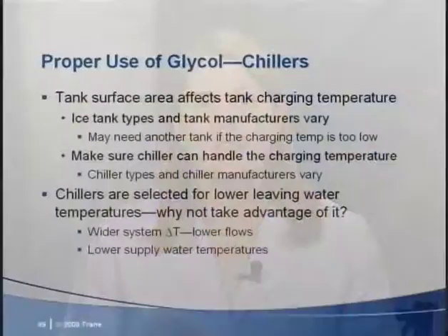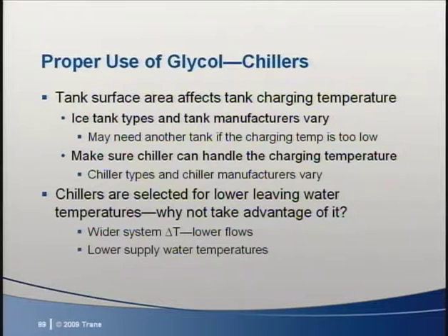We would repeat this process for another pairing of chiller and tank. In our case, we also selected a 70-ton chiller matched up with 3 tanks. One thing to watch out for on the chiller and tank selection is the flow rate at the charging temperature. The limitations on operation will be different for different chiller types and potentially for different tank manufacturers. Work with the manufacturers to make sure the chiller and tank selections are appropriate for the desired system design.